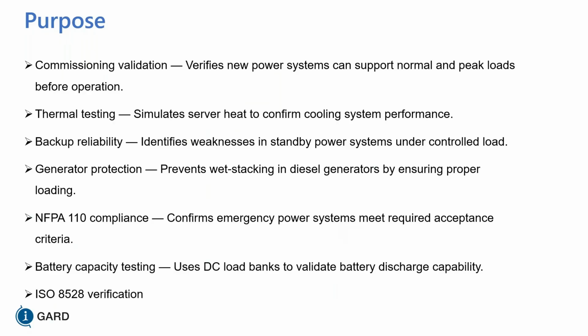And you're going to do thermal testing. Some areas require you to test the HVAC and the cooling system of a facility. So you can use load banks to determine if the cooling system is good enough for that facility. For example, we can put in a load bank to simulate a load. So not only are we testing the power source, we're creating heat so that you can test another facet of the building operation to ensure that the temperature is suitable and the HVAC system is suitable to cool that area down.